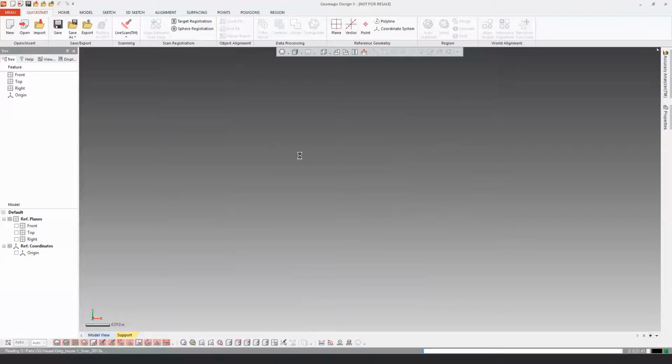And I usually pull in, if there's multiple scan settings, as I'm starting a project, pull them in generally one at a time, just to see what's going on, to see if maybe the data was processed or clipped, or if it is indeed full range on the scanner and there's a lot of extraneous stuff on the outside edges we don't need. So as this is processing here, again, we're looking at scan data sets in these long-range data where we're looking at 10 million points, if not more, at a shot from a long-range scan.